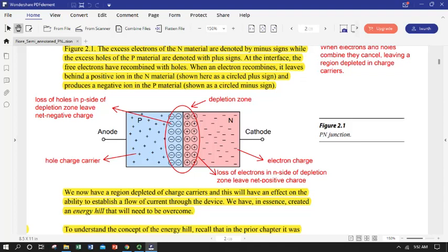So, if we heated the material up, there'd be more here, but nothing compared to what we would have in a doped material. So, if you think about relative conductivities, our N-type material is probably pretty conductive because we've got all these extra electrons from our dopant. Our P material is pretty darn conductive because we've got all these extra holes from our trivalent dopant.